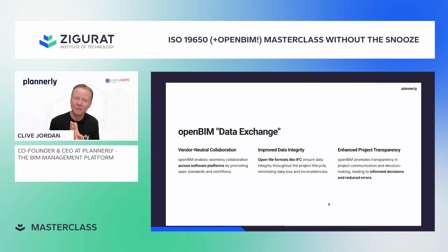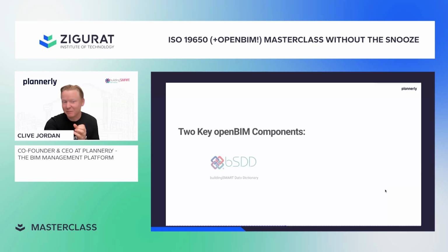But if you share it as a PDF, then people see exactly what you wanted them to see. In this same way, if you're sharing files using IFC, the desire is that you are sharing the right set of information in the right format so that they can use it in their tools and their workflows in a way that is seamless and enhances collaboration, informed decision-making, and really does reduce the opportunity for errors.